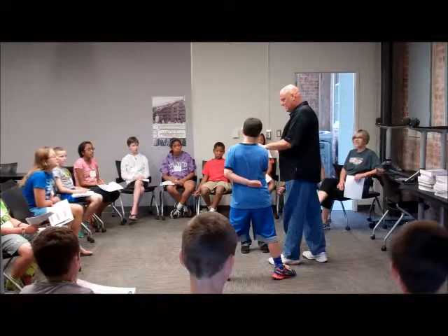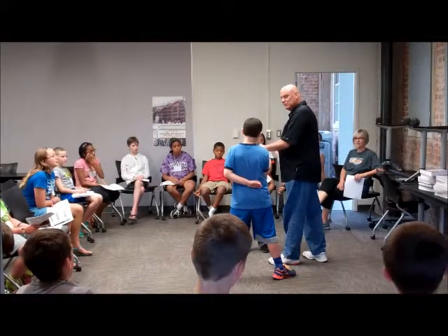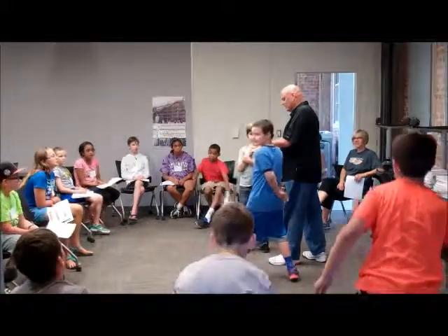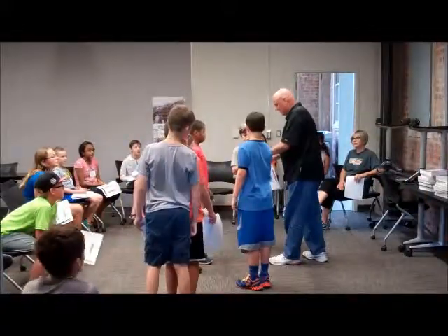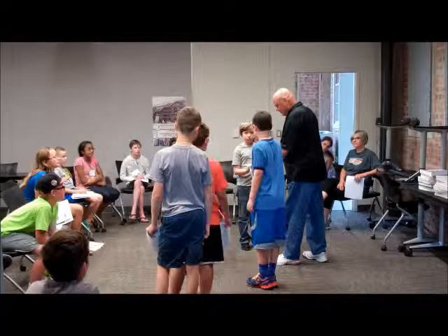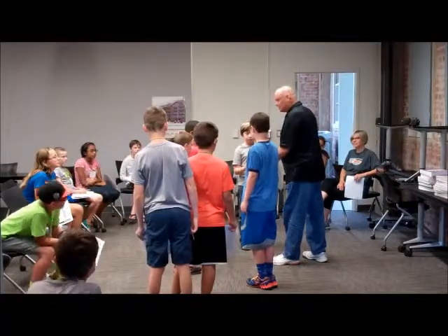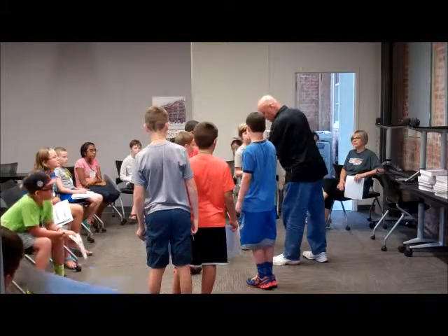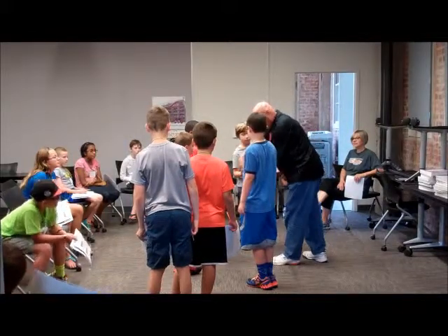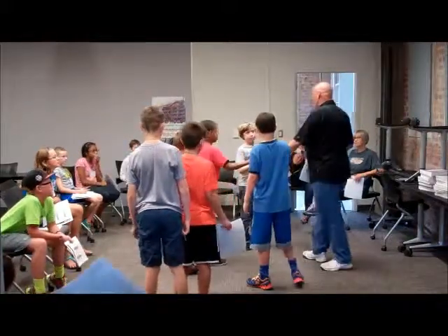Can everybody see that? Can I push it down and move sideways? Everybody come up here for just a second and watch. You guys put it down just a little bit so everybody can see it. Now watch what happens when I push it. Instead of going down, it goes sideways like that. It buckles. And when I hold on to it real tight, watch what happens. It twists. You see this one goes that way and this one goes that way. Now why does it do that?